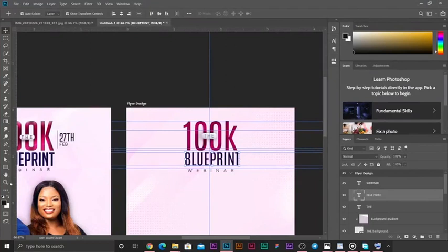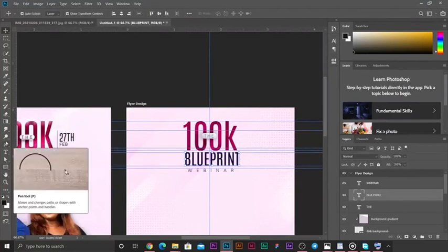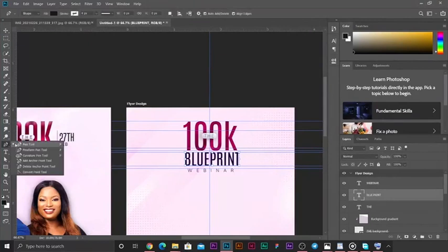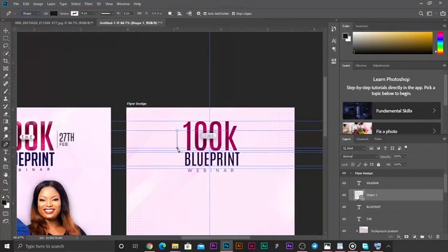So to make this vertical line, there are two ways we can do that. We can actually use the pen tool. Make sure this has to be in shape and not part. So I need to come over here to the top line, drop a point, come over to the bottom, drop another point. So Control Z. The point is not straight, so I need to Control Z, or I'll go to the history to undo that. So I can use my shift key to get a straight line.